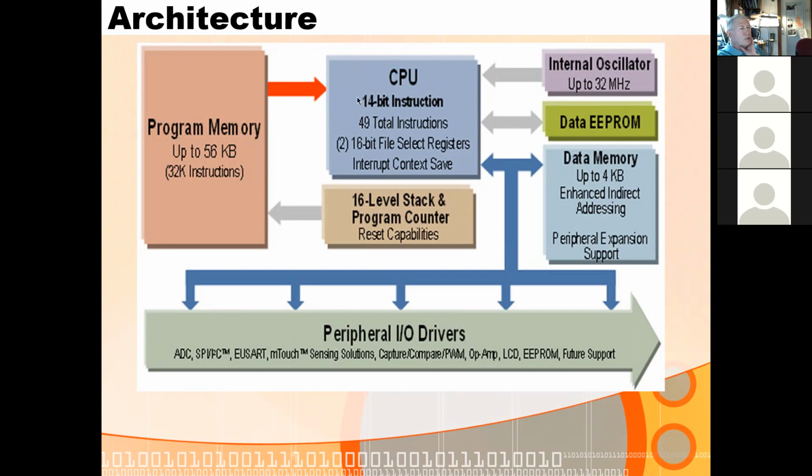The CPU, every instruction that's executed is always 14 bits. Now, there are many microprocessors that have variable length instructions. With one of the old Motorola chips, you could have an 8-bit instruction, a 16-bit, a 24-bit, a 32-bit. I think it could have as many as 5 8-bit bytes, or maybe even more than that. In the Freedom board that we use in Micro 2, all the instructions are 16-bit instructions, except there are 6 32-bit instructions. So they're variable length as well.